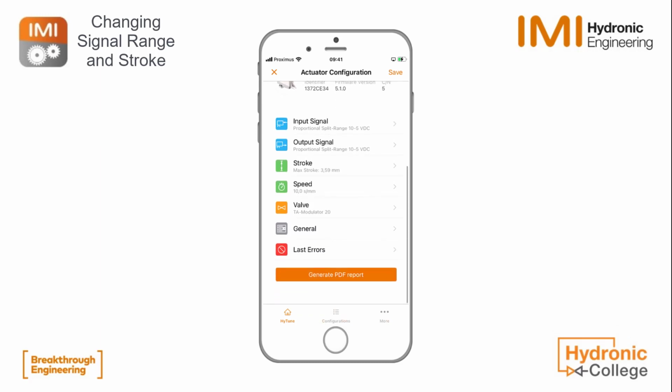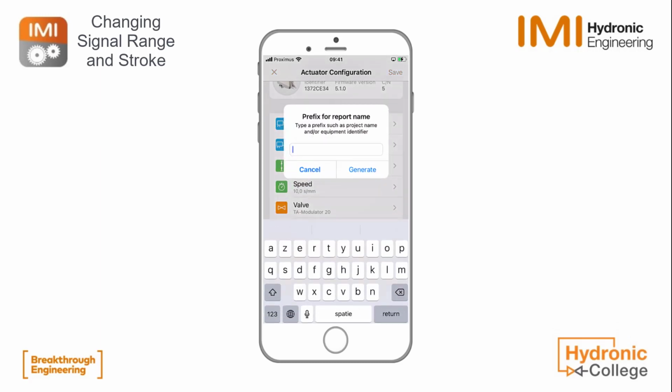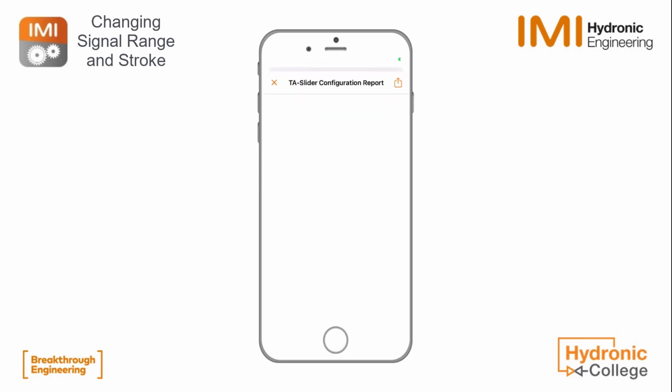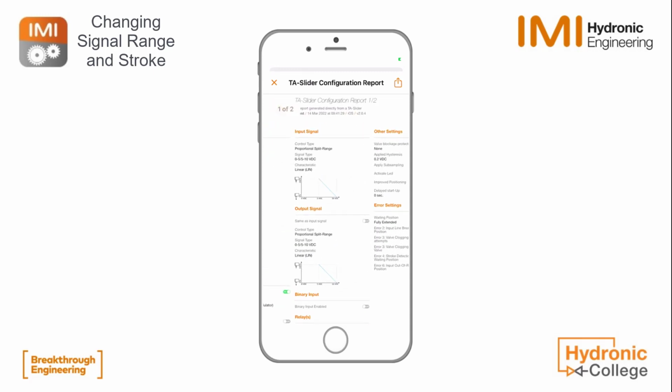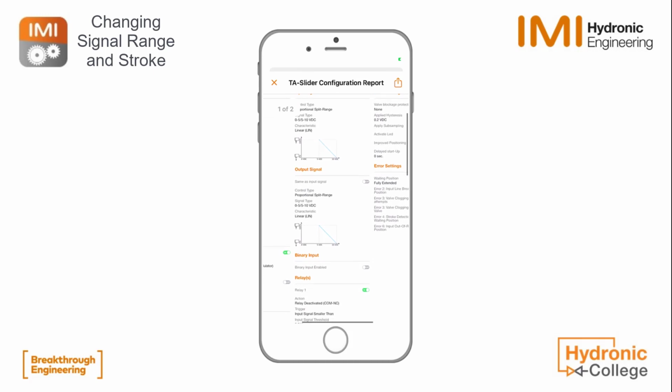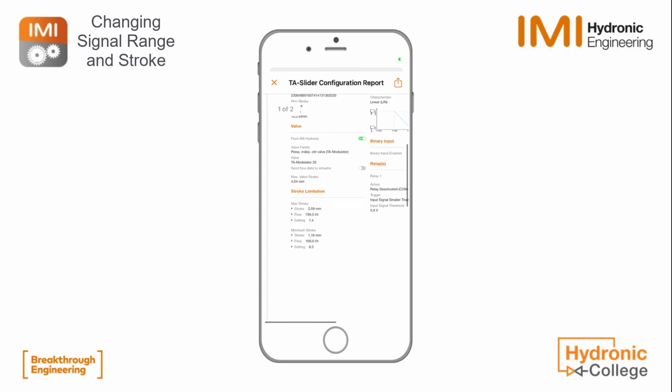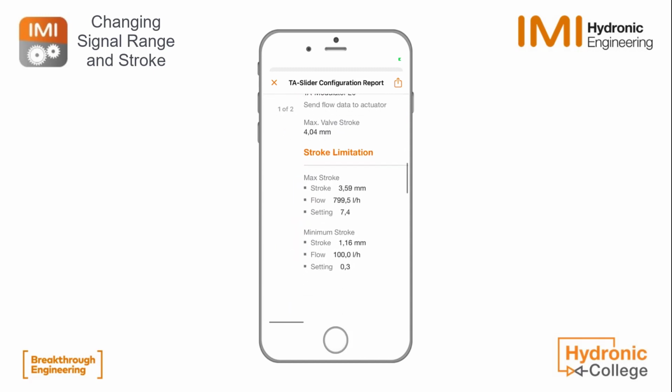To see how we have set the current settings, we can generate a PDF report. You just simply click on generate PDF report, and you name it, for example here with test, and then you see the settings we have changed or we have entered in input signal, in output signal, and all other settings in one overview. Voila, like here.